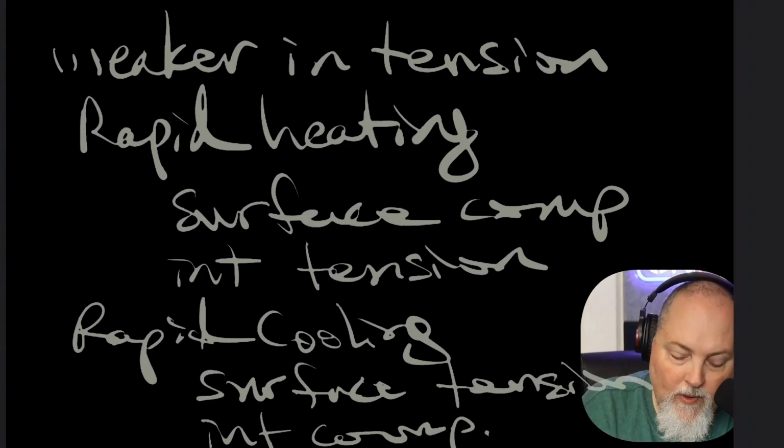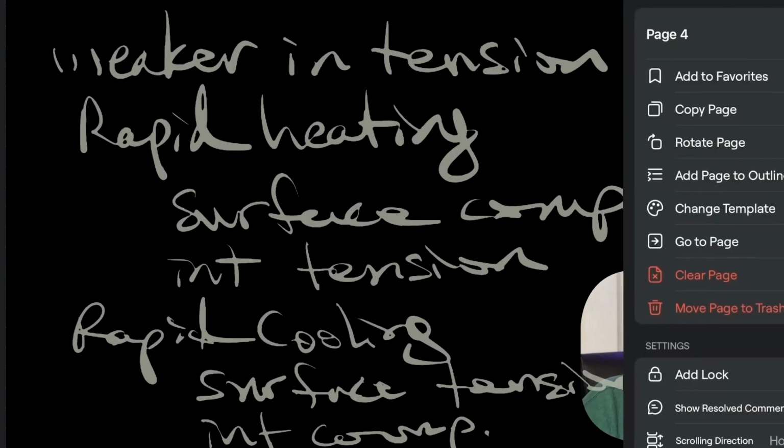And what gives us those different temperature gradients? What are the things that affect how bad that is? Thicker walls mean bigger temperature gradients. If I have a thin wall here, I have the same delta T, but the gradient is that delta T, that change in temperature across a thickness.